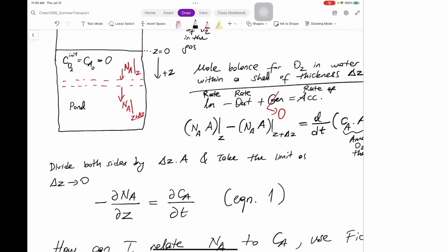Yes, thank you. You can make similar assumptions for heat transfer as well. You can heat up a wall from one side if the wall is very large and you're talking about short time intervals or the temperature near the surface, then you can make this assumption. In this case, I know that the pond is going to be orders of magnitude deeper than 2 centimeters.